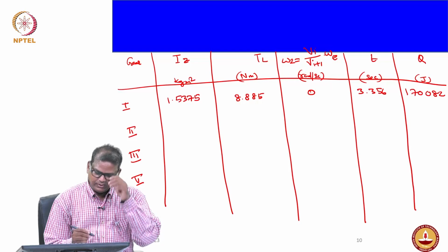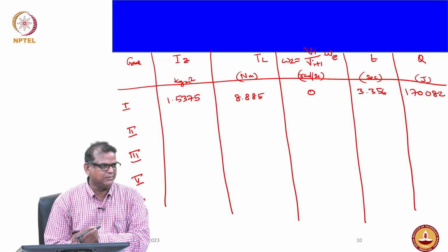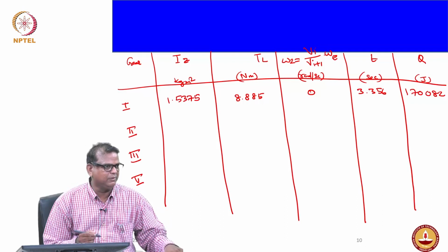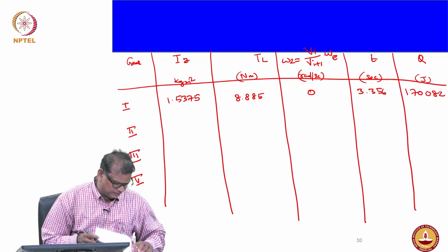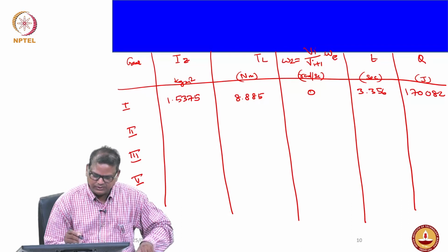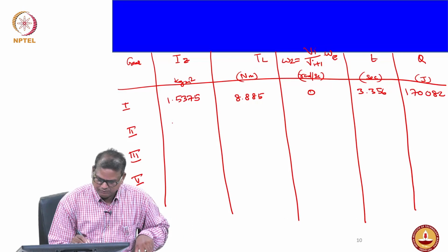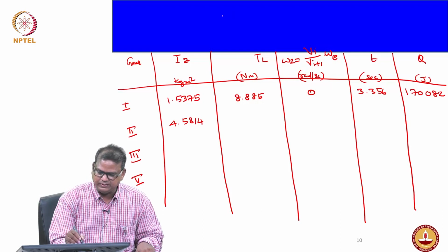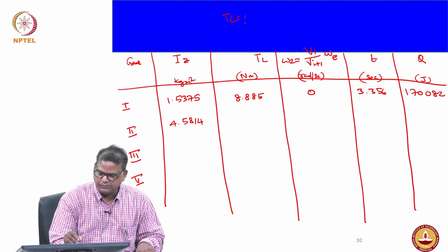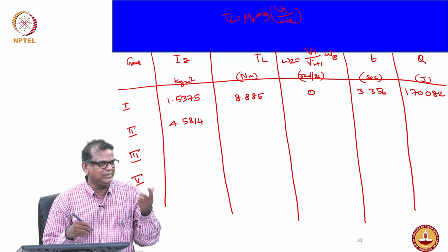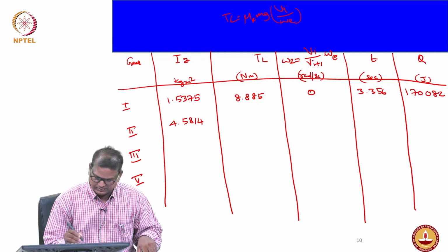So, now you have to find out for the second gear. In the second gear, Vi will change; again we have to refer to your Vi with respect to second gear, it should be 22.505, that is the Vi. So, when you substitute, you will expect the value 4.5814. The torque also, Vi will change, right, TL equal to mu r mg Vi omega engine speed. So, the corresponding Vi substitute; obviously as the velocity increases your load also will increase, right, torque load will increase 15 Newton